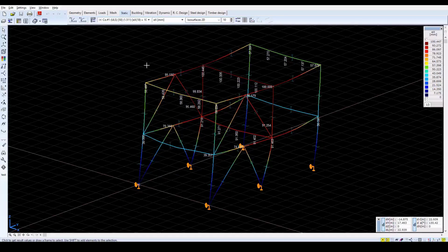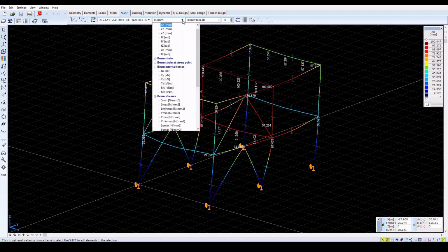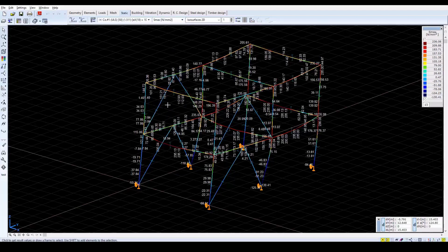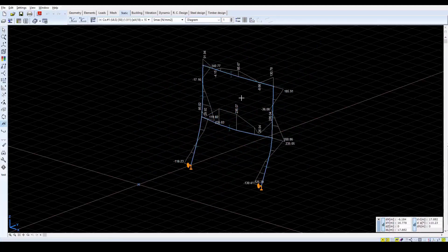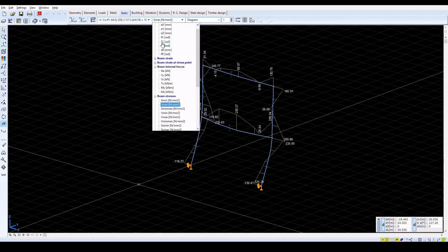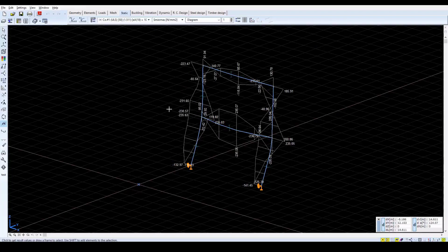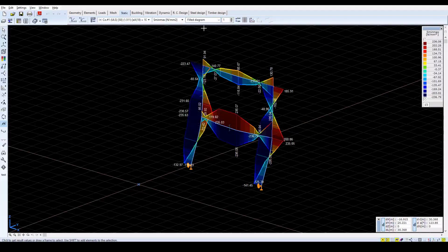With the analysis completed, the displacements are shown on the deformed shape for the last increment, the 50th. Let's examine the progression of the plastic hinges in the intermediate frame. For better visualization of the intermediate frame's results, the corresponding part is activated. Select the stress minimums and maximums results display, S-min max, and the filled diagram mode.